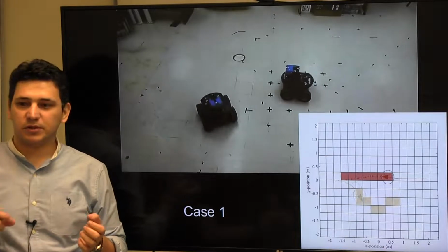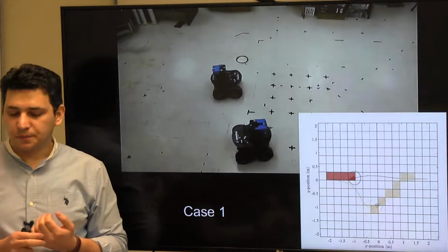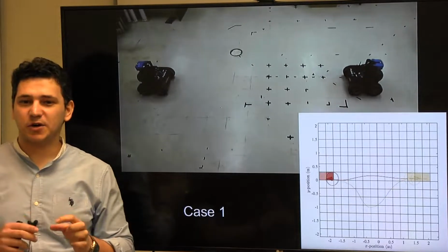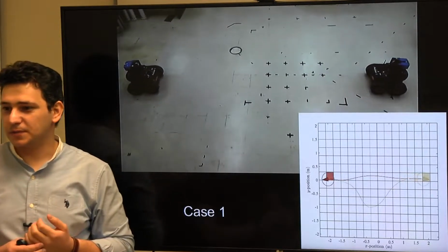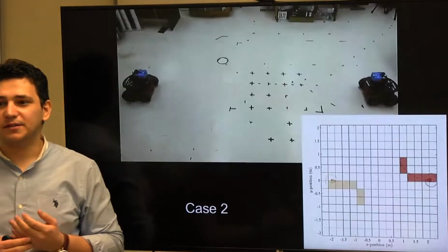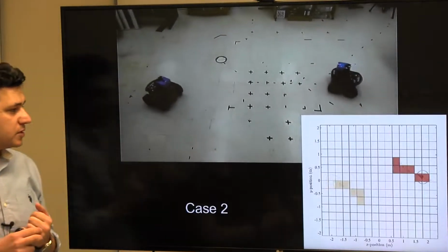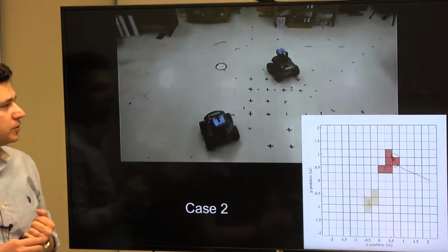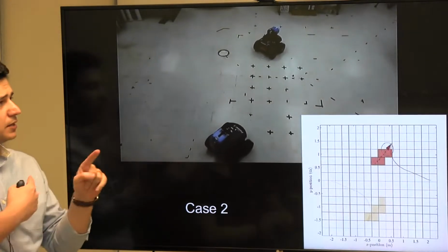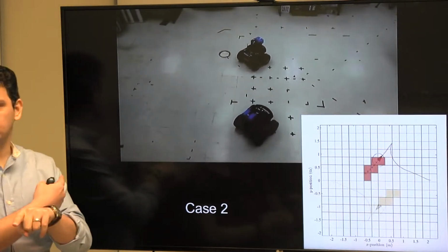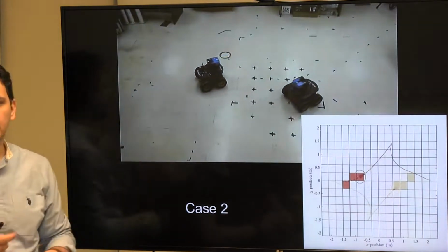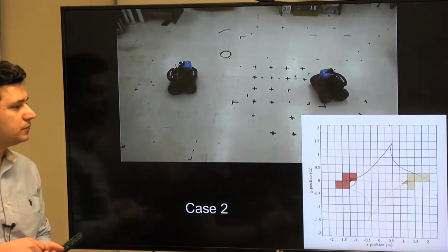So you remember the part where we talked about obstacle avoidance? We assume that the obstacle position is constant for all the prediction steps, right? Here the obstacle position is basically time varying, right? So this was the experiment. We did 4 experiments where the robots, in the first one, just exchanged positions. Now they are exchanging position and orientation, right? So you will see them avoiding each other and converging to their references as well, right?